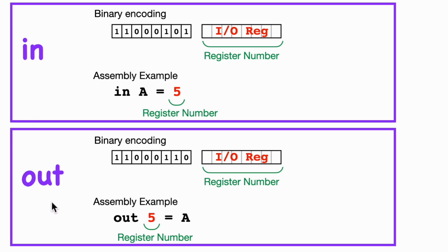All interfacing between the core and peripheral devices is done by reading from or writing to the so-called I/O registers. There's a set of up to 256 of these I/O registers, so 8 bits is adequate to address any one of these registers.